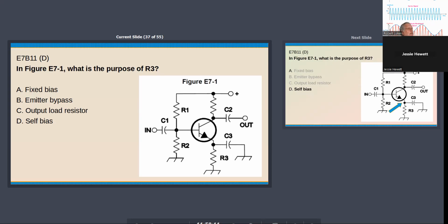So you're just selecting when you want it to operate. Yeah, it may not be just an on and off scenario. If it was a saturation switch, then you have the bias set so it's either at saturation or cutoff, and then your input signal will go to the opposite state. So it's either one or the other.